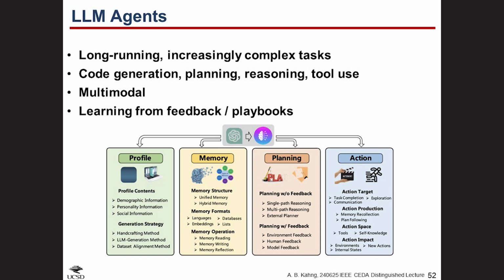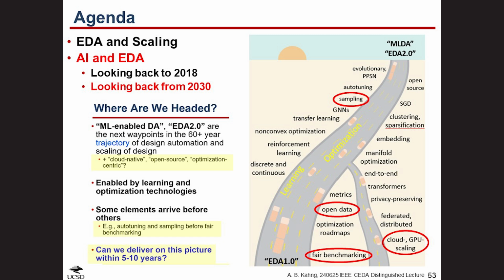And here's a recent work that makes early design exploration and assessment faster. It's example number 3 of optimization. DG-RePlAce is a data flow aware, GPU accelerated version of OpenROAD's current placement engine, which is called RePlAce. And this slide shows results in GF12 ARM enablement for a quad-core RISC-V called BlackParrot from UW. The new placer is compared against RePlAce and against DREAMPlace 4.0, which is the previous state-of-the-art GPU-accelerated global placer. Maybe Evo will say it's the current state-of-the-art, who knows?